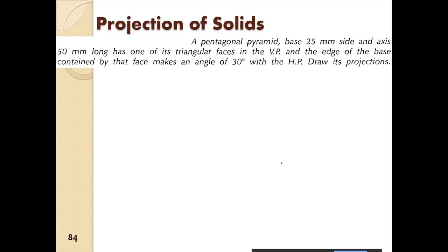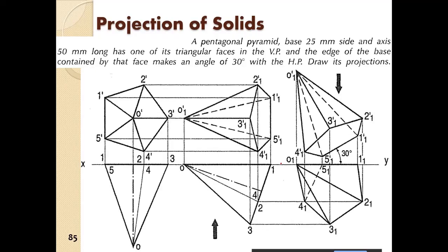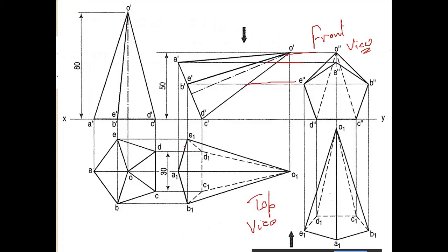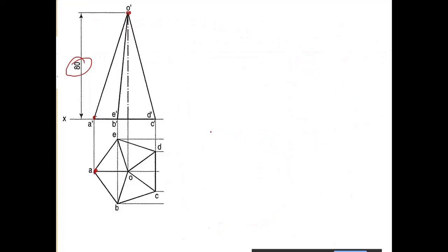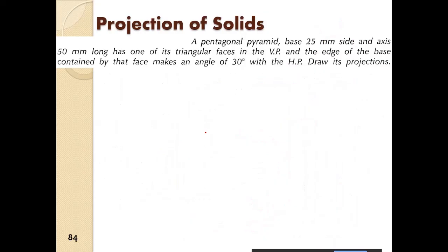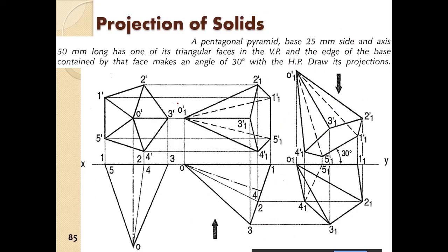An edge of the base is contained by that face, making an angle of 30 degrees with the HP. Draw its projection. It is straightforward, just as in the case we have discussed. So the first step is we get the pyramid, we draw the front view.